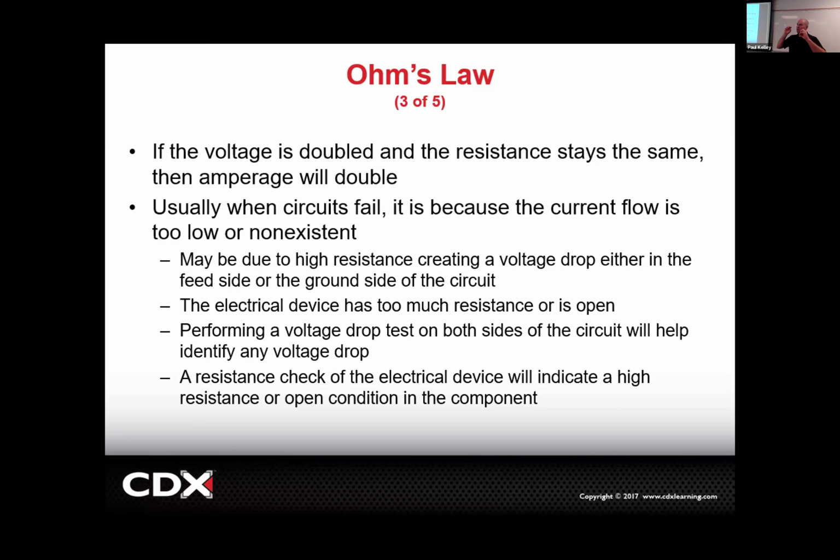It's kind of weird if you think about it, because if your resistance is infinity, your amperage would therefore have to be 0, right? So that's why OL makes a lot of sense to me as out of limits. It's kind of like infinite. All right, and that'd be if the bulb is out completely. So we can already anticipate we're going to have excessive resistance, probably an open.